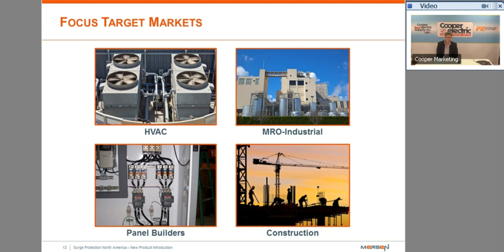So by installing an SPD, in many cases, it can solve your problem. It's a really low-cost solution for any of your customers that are complaining about PLCs that are failing or the programmable logic getting corrupted, and they can't pinpoint what the problem is. This is a great product to put in, and many times will solve the problems.